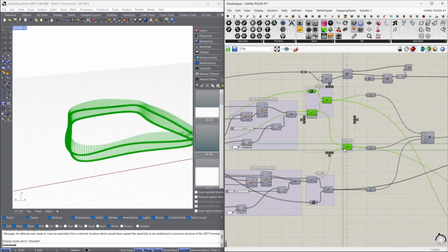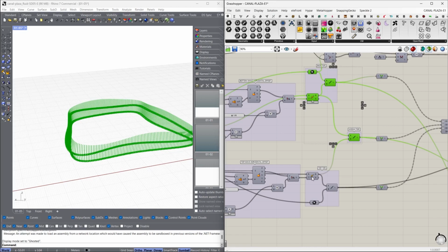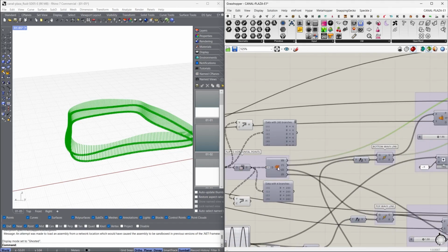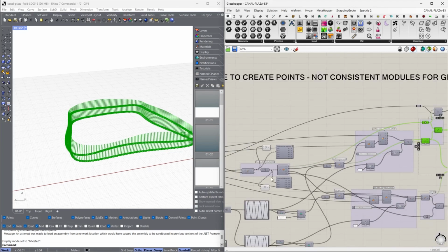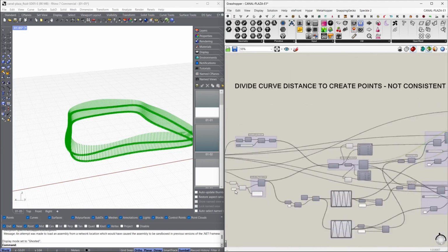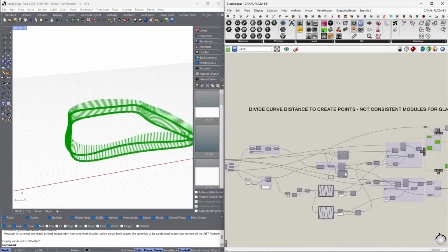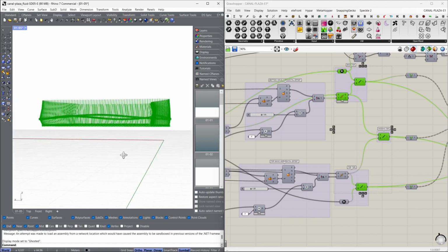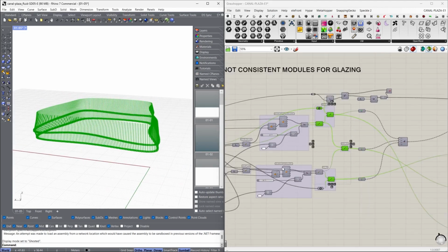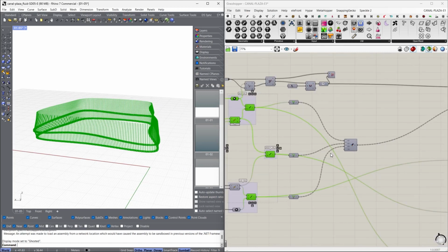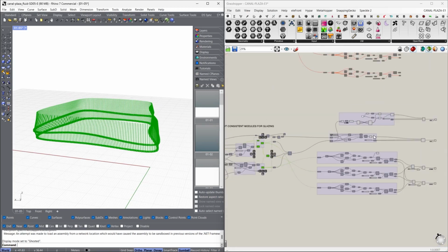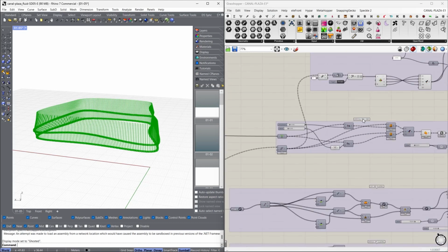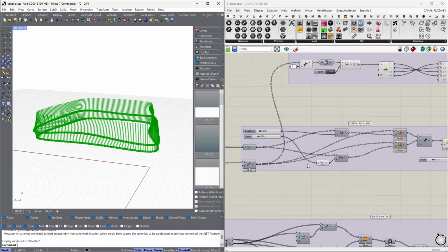Then we've got a middle tier which sits on top of that, and then similarly we're using the wavy points we generated, and the topmost row, which is still coming from right in the beginning, where we've got a very simple straight row of points, which is a divided up curve. And if you connect all of them, you get the top segments. So we've got these 3 sets of lines which generate the different segments of the facade. From that, we just move on to creating the vertical fins from these guys.